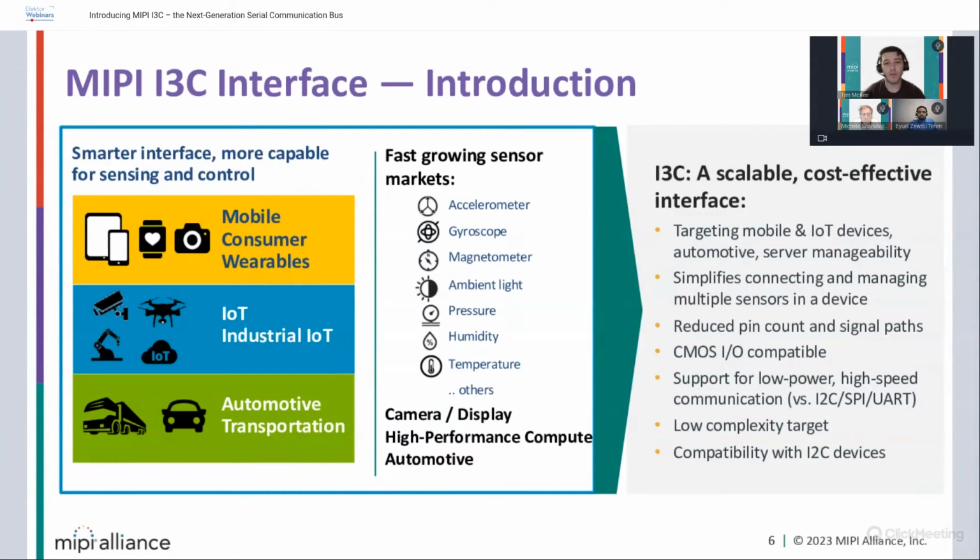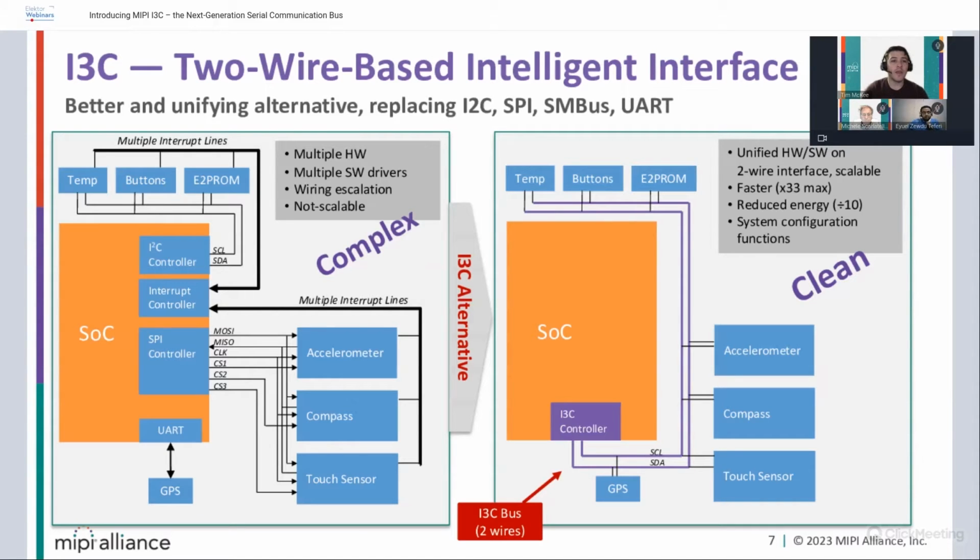And we did build this in with backwards compatibility in mind, and so there is a level of compatibility built in I3C with the I2C interface, and so that you are able to have a mixed bus situation where you have both I3C and I2C devices on the same bus, which we'll get into more detail on that later. So what has I3C brought to us? Well, previously, if you looked at kind of a SoC die design, it was pretty complex.